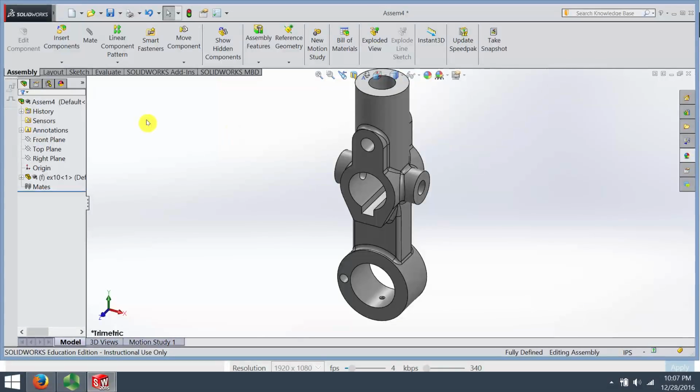So the way to get started is you're going to insert new components. So I'm in the assembly toolbar. I come up here to insert and go to insert new part. First thing it comes up with is a little green check mark. Now, a lot of times people will just go, well, I don't know, I guess I'm supposed to put that somewhere. Feel free to look down here, and even like in the old AutoCAD days, it'll give you some clue about the command you're in and what it's asking for.